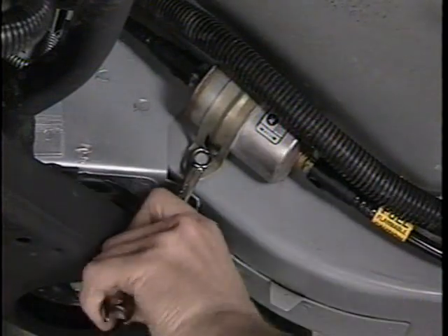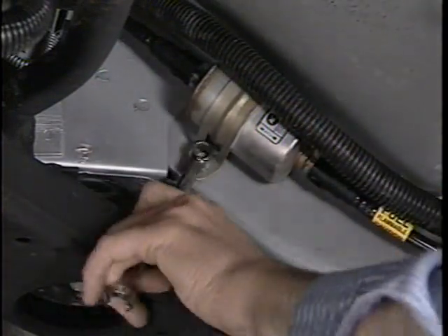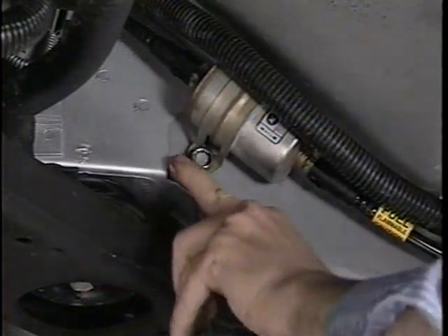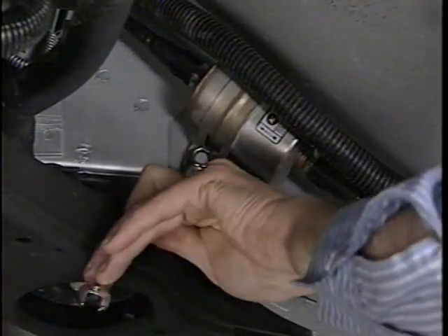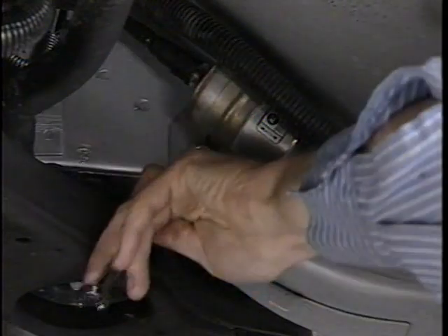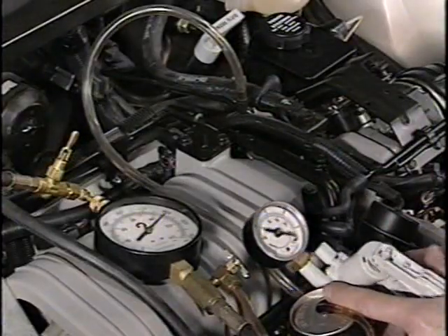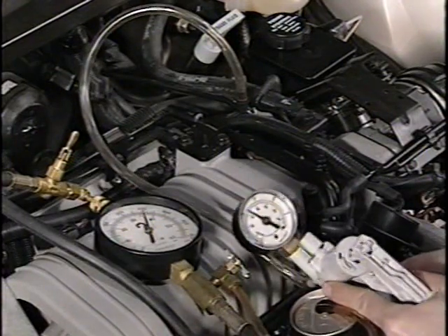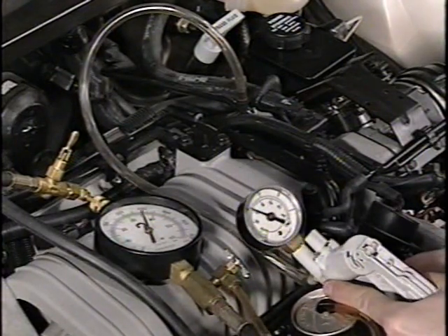However, if fuel pressure is low and there's a hot hesitation, sag, or low power complaint, it's assumed that when the symptom diagnosis chart says to check for low fuel pressure, you check the fuel filter, along with fuel system components such as the pressure regulator, to find the exact cause of pressure loss.